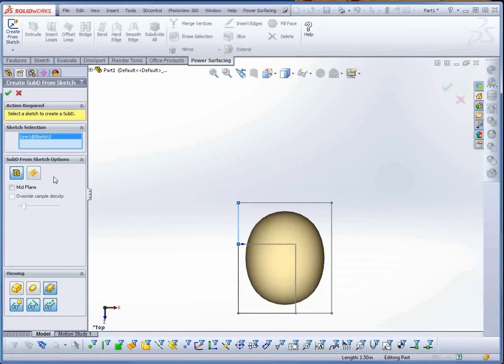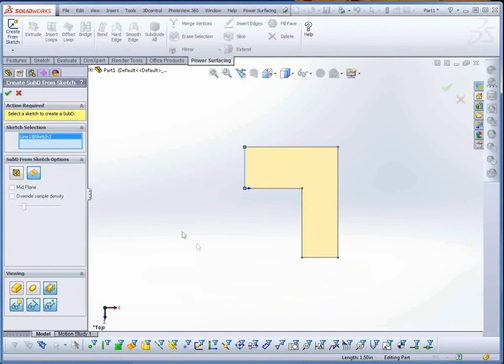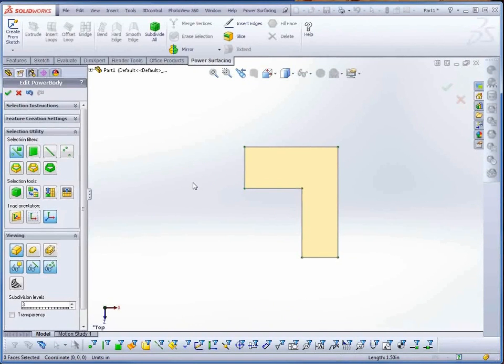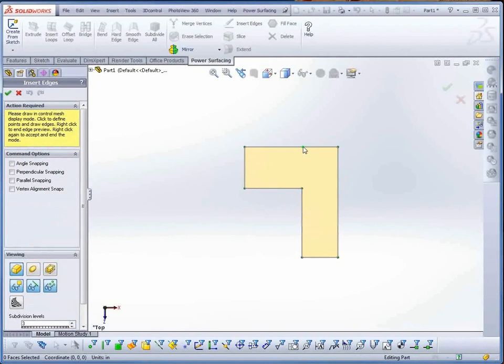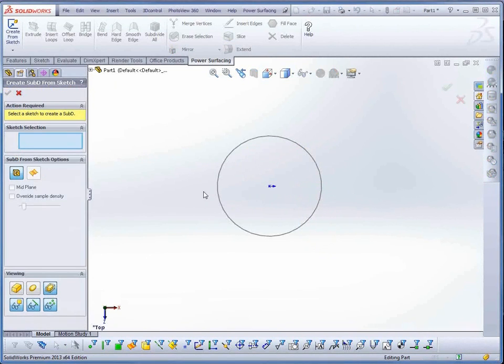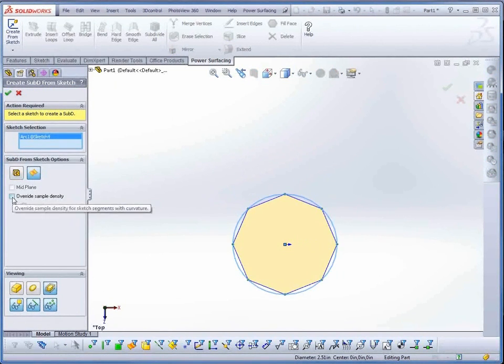The other sketch option is to use the sketch to create a surface. This more advanced option will allow for more than 4 sides, but may require you to manually retopologize the resulting surface. Curved edges will be recalculated based on sides per 360 degrees, so once again, keep things simple to start.